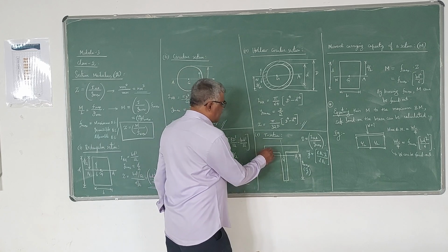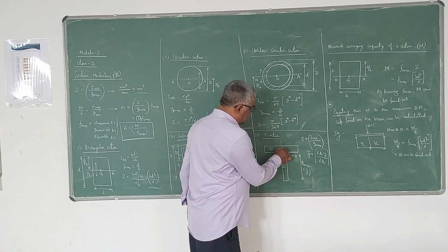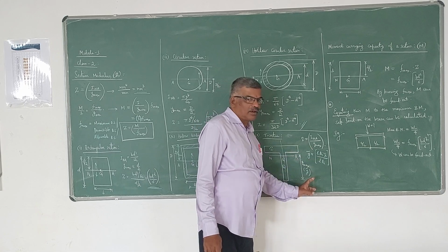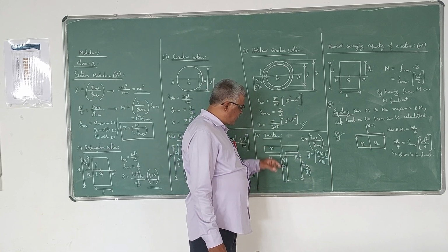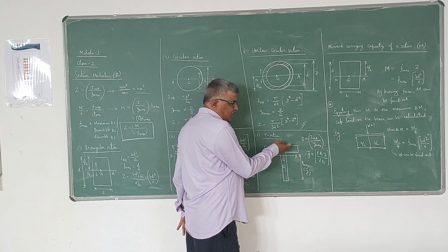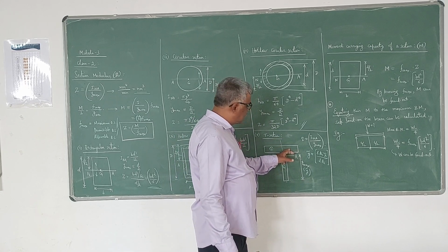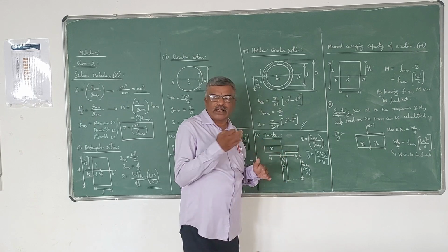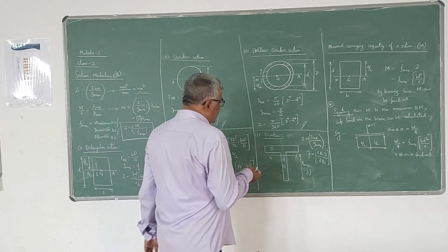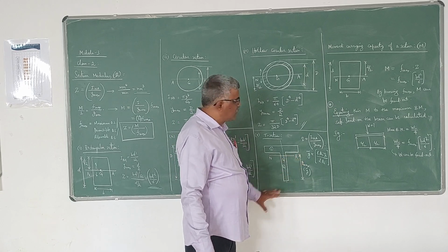So here this is one rectangle, and this is another rectangle. We have to find out the areas, and locate the centroids of these rectangles separately. Those distances are y1 and y2, and if you substitute in this formula, you get y bar. In this case, you can observe that this length will be more than this one, because the area is more concentrated on the top, in the flange portion of this section. Your centroid always lies in the region where the area is more concentrated. That's why this is not a symmetrical section about the x-axis. So Y max is this one, y1 is Y max.